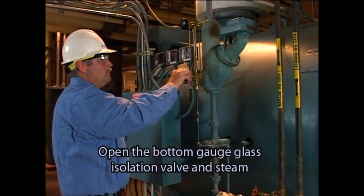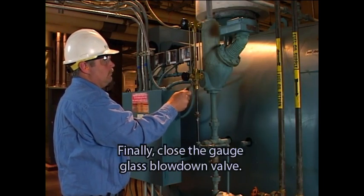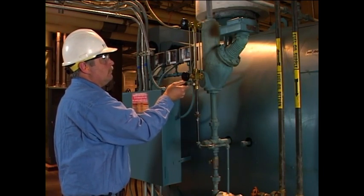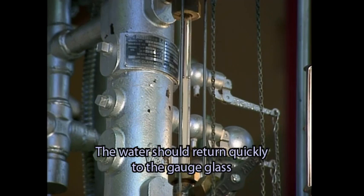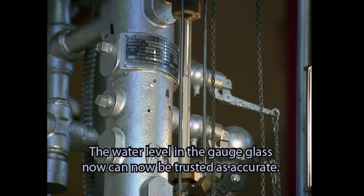Open the bottom gauge glass isolation valve and steam and water should flow freely into the gauge glass. Finally, close the gauge glass blowdown valve. The water should return quickly to the gauge glass and flow without interruption. The water level in the gauge glass can now be trusted as accurate.